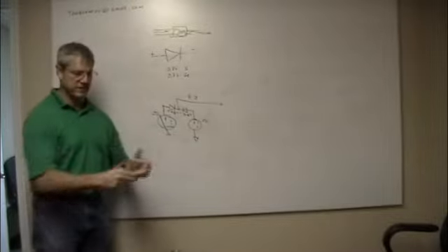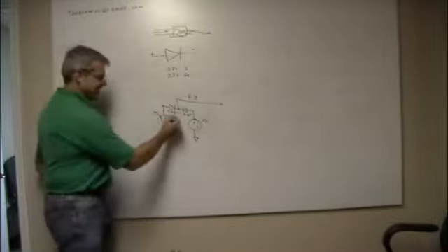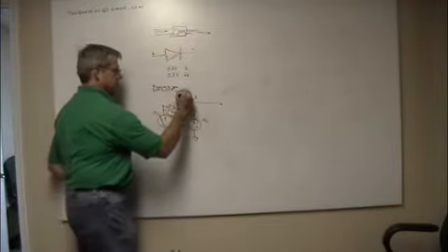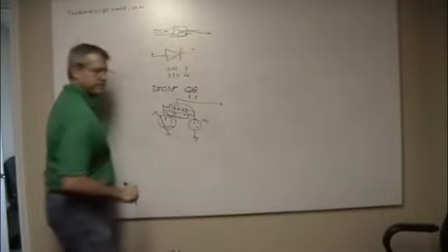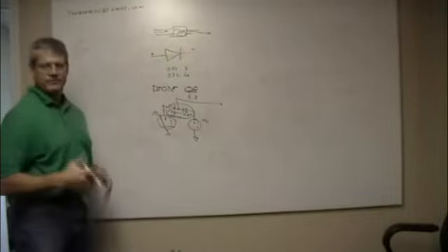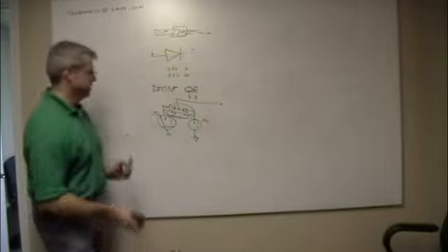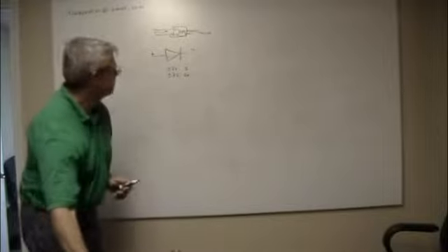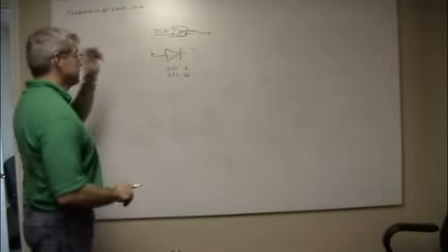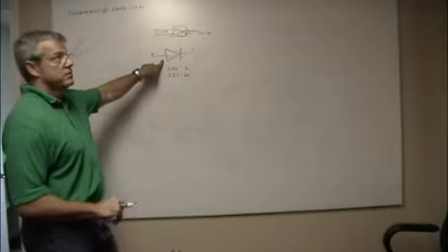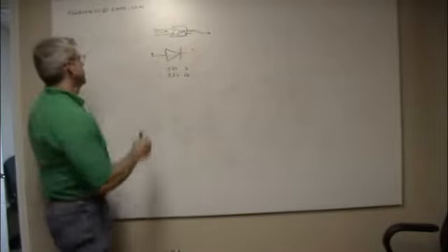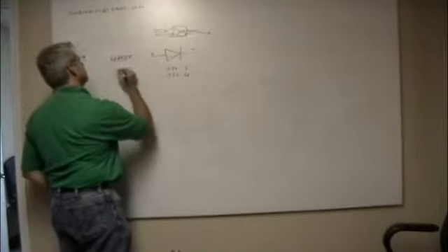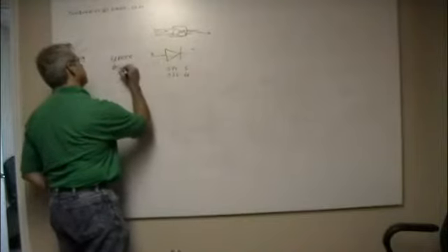I'll take two 5-volt supplies, plug them together. This is called a diode OR, because it lets this one or that one through. And it keeps you from letting the smoke out. Now, the next, so this is a barrier diode, also known as a rectifier diode.